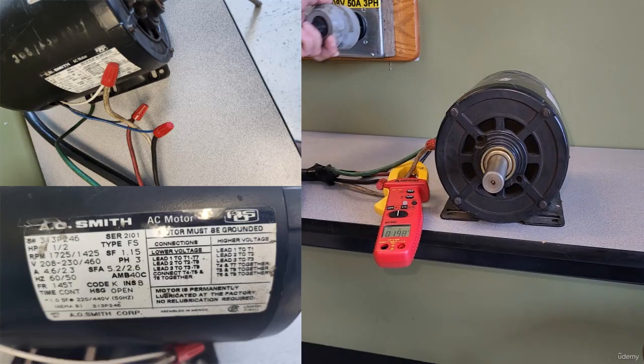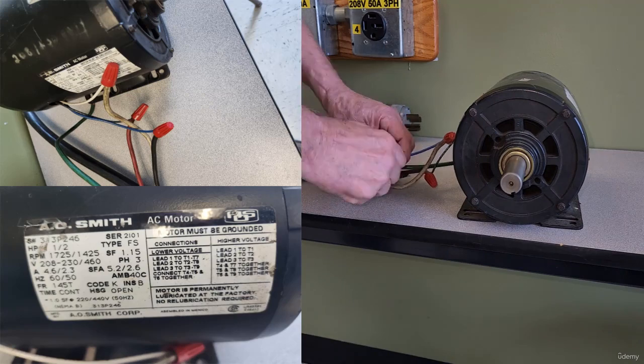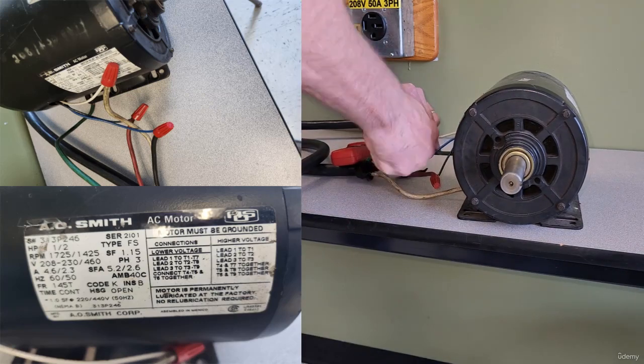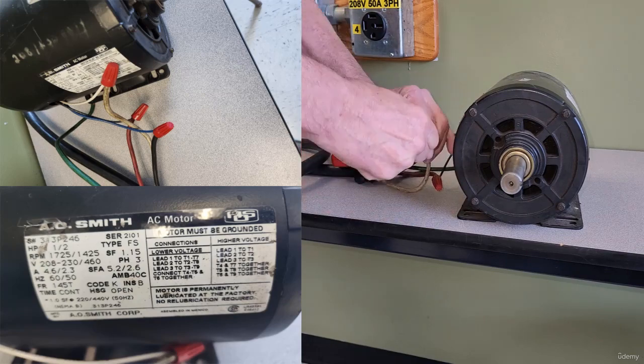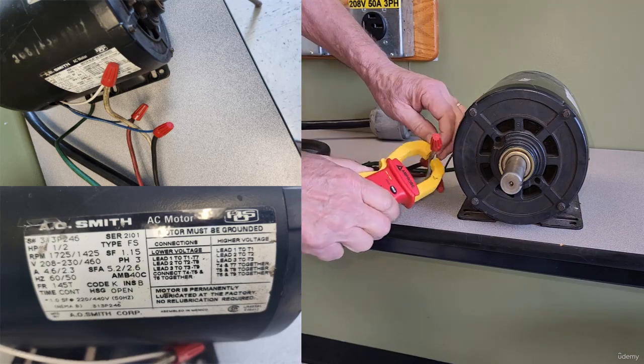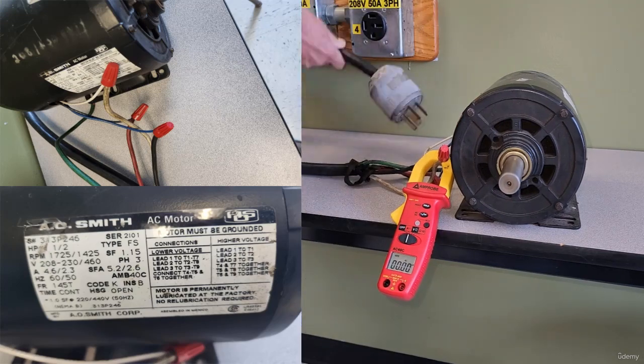Three-phase motors can run in the wrong direction if wired incorrectly. Don't worry, it's easy enough to change the direction. You just swap two incoming power lines until the motor runs in the correct direction. The phase shift determines the starting direction of the windings relationship to the rotor.